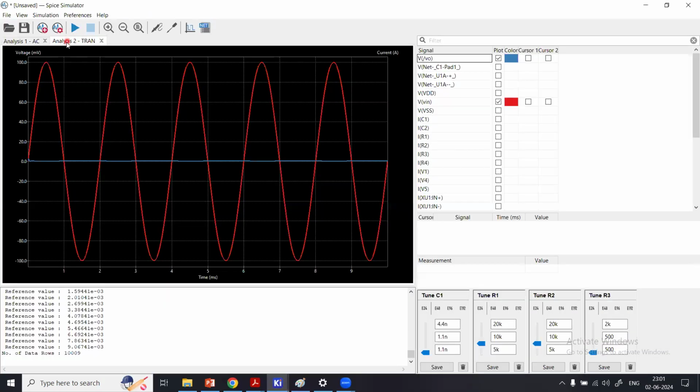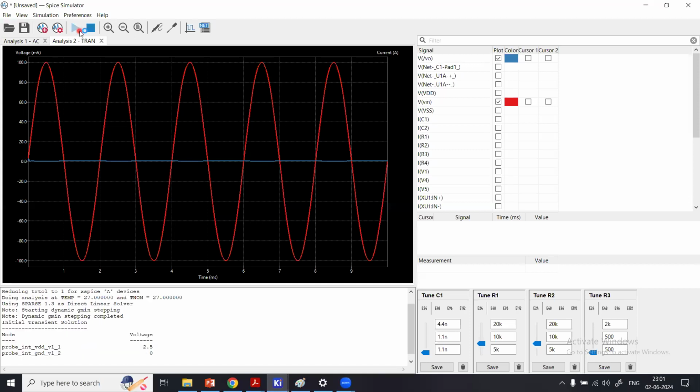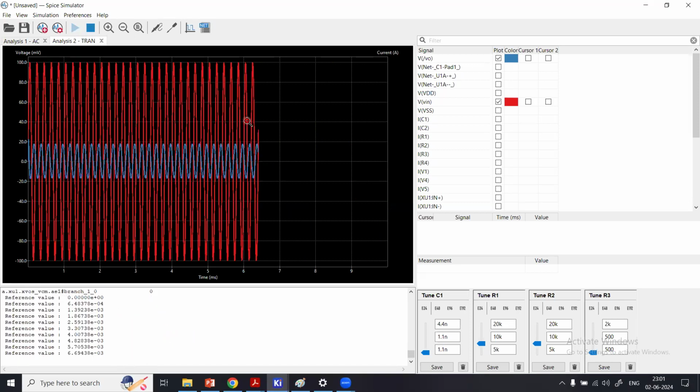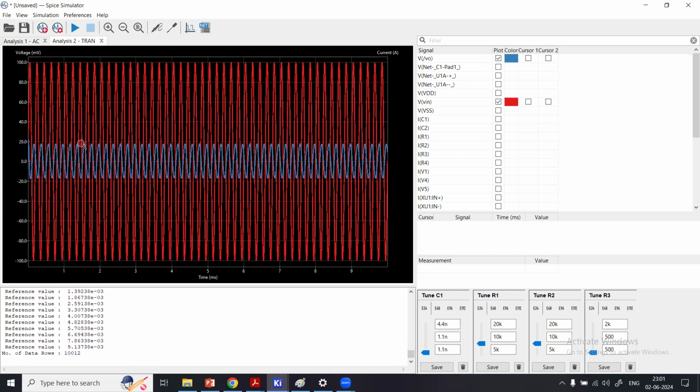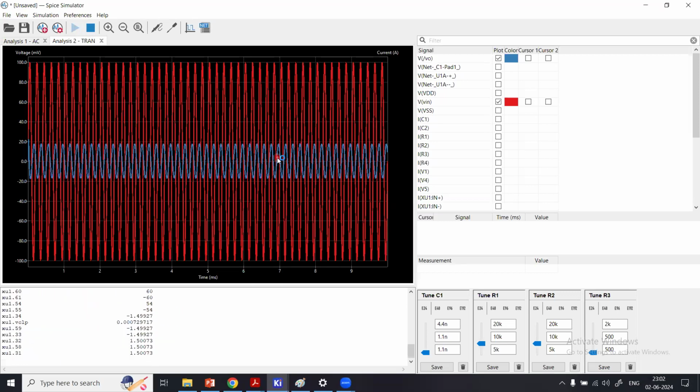Let me show you, you can see that again here by clicking here. Here is the cutoff frequency. So above 10 kilohertz, you have a higher gain, right? Gain of 2. So go back and now simulate again and see if your signal will improve. Yes, it got improved, but your output signal in blue is still attenuated, right? So now what I'll do, I will just adjust the 10 milli. Instead of 10 milli, I will say 5 milli. And now click run simulation.